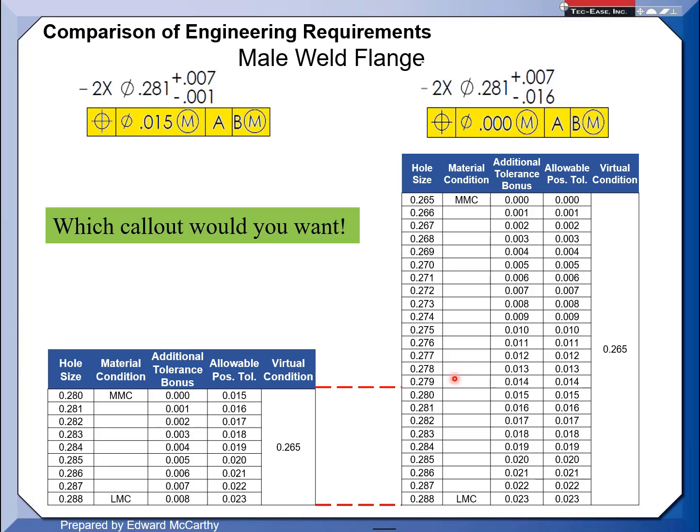And I have taught manufacturing engineers, showing them this, that with these two here I'm definitely giving them a lot more variability in centering up the process. Either way, if they go to either of the limits, they've got to be careful of non-compliance. If they start making holes at this upper limit as large, they've got to be careful, because if they exceed it, there's nothing they can do to make the part compliant. It's a non-compliant part.